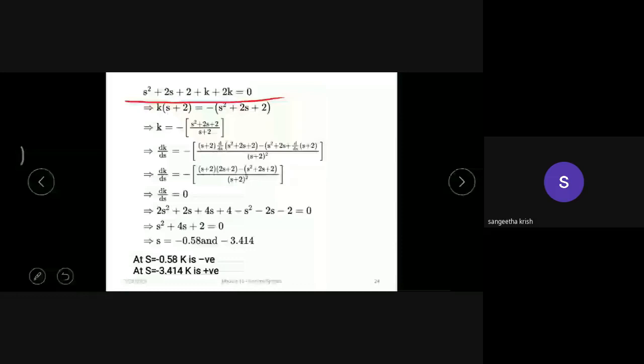It is not so. Even 1 point can be a breakaway, and the other point can be a break-in. It depends on the root locus. So to get the exact breakaway point, take these values of s and substitute back in the s equation. It's one of the toughest processes. Without a calculator, you cannot proceed with this, but anyhow, logically, you can think and act.